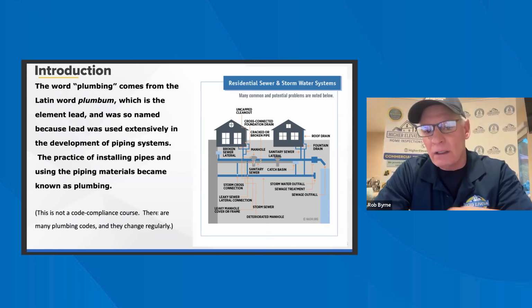Water leak catch pans. You see this a lot when the water heaters are on a floor up on top. You don't want it to leak down. If it's in the basement, you don't really see these, but more so in condos, if you have a water heater and it's a multiple floor, you'll see that. In the basement, some people do it, or there's a floor drain right there. They're not too concerned with it. But again, you could inspect it if it's there. If it's rusted or clogged or anything, you just call it out.